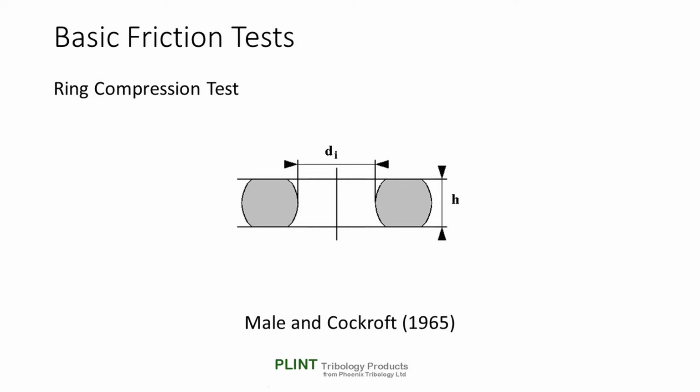the non-compressed state. As the interface friction increases, a transition occurs, causing the ring material to flow both outwards and inwards, respectively increasing the outer diameter and reducing the inner diameter. Because the inside diameter increases with low interface friction but decreases at high interface friction, measurement of this diameter provides a sensitive measure of the friction.